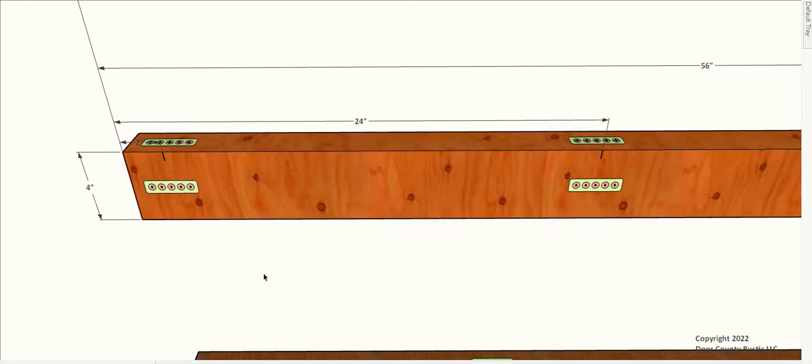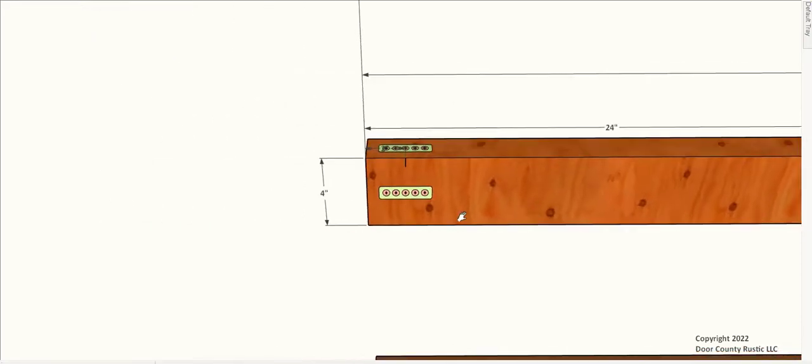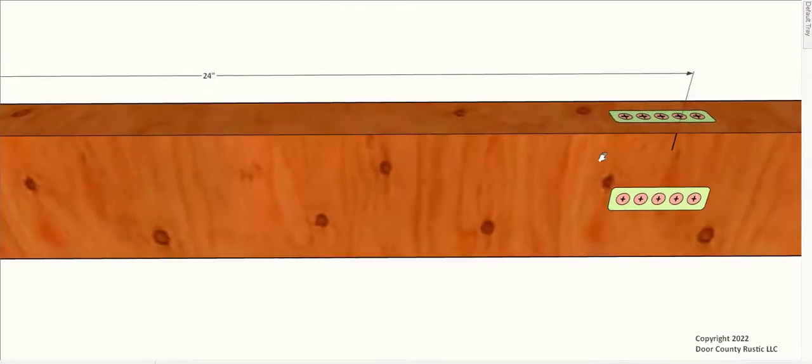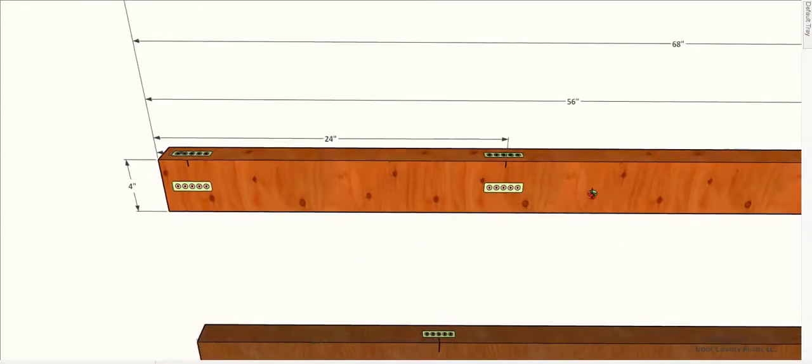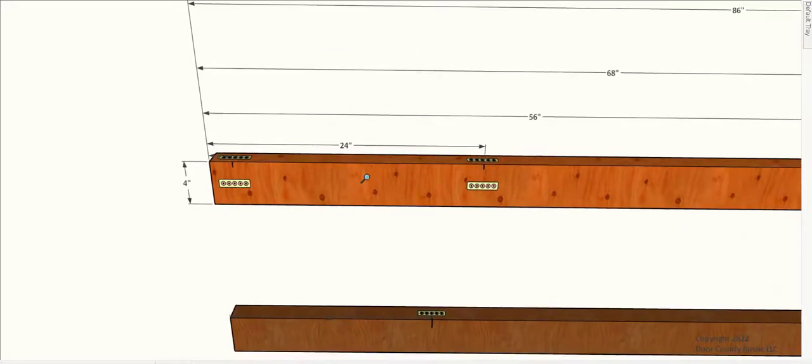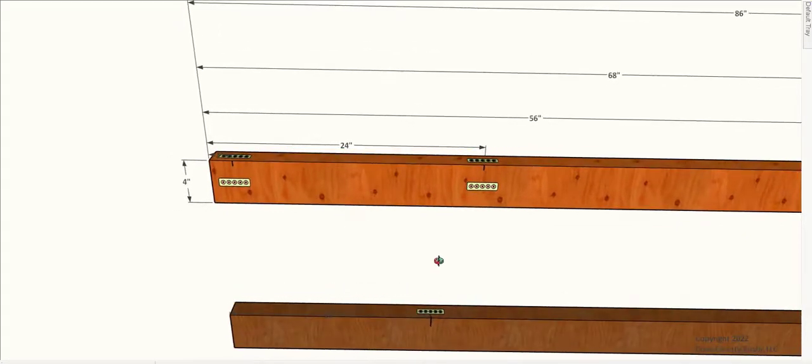So this is different than what a carpenter would do on the house. They're going to lay out a bottom plate and a top plate. They're probably going to put them together and then mark to the left edge or the right edge, probably depending on whether they're right-handed or left-handed, but they're actually going to mark from here to like here-ish, or wherever that board is going to come. They're going to do that with each one of those. Instead, we're marking to the center of each one. I do have a 4-inch board. We know that already. We have a 2-inch board. So that's the dimensions for there.